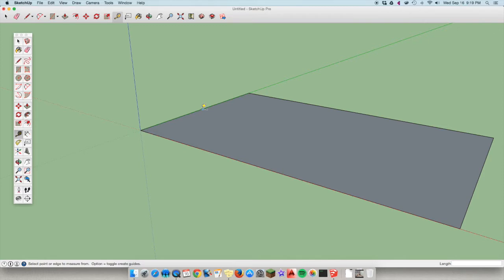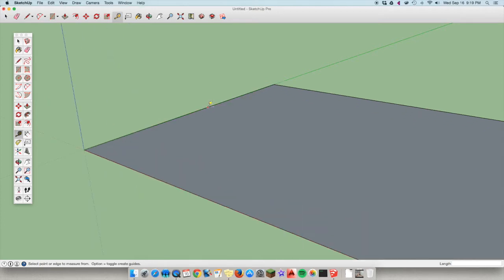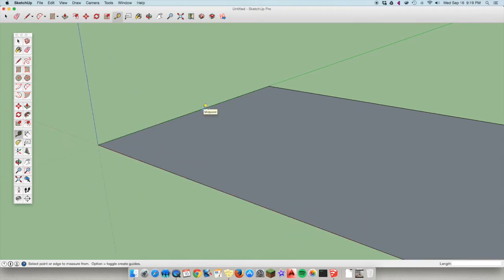We need a garage that's going to come off of this side of the house. We're going to build it all in this shape, and then this side's going to be the rest of the home. So if you take your tape measure tool and move over to the midpoint, you'll see a little blue dot, the midpoint of this wall. Click it and start moving in this direction, and you'll see this dashed line start to form. As I'm moving, it's keeping a nice straight red line, which lets you know that I'm headed in that direction.